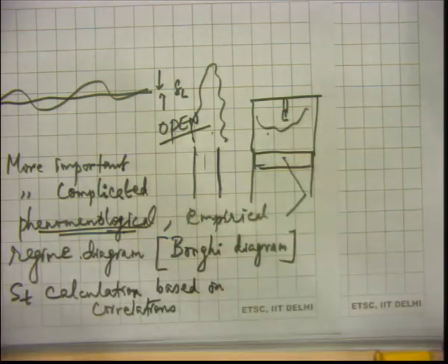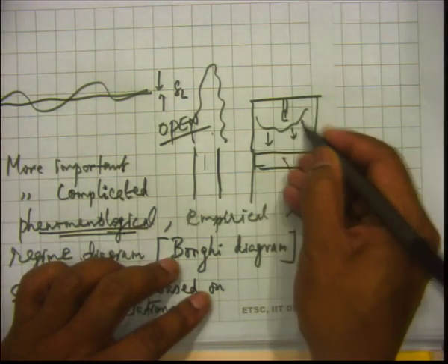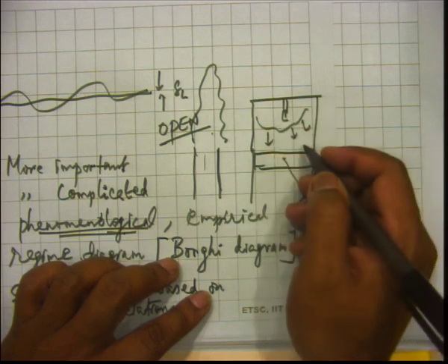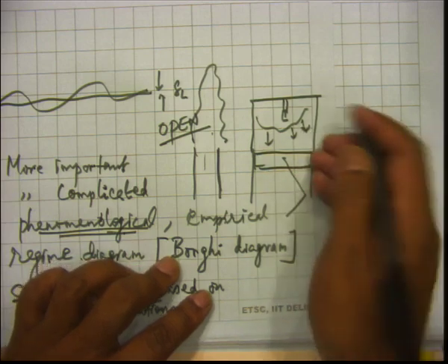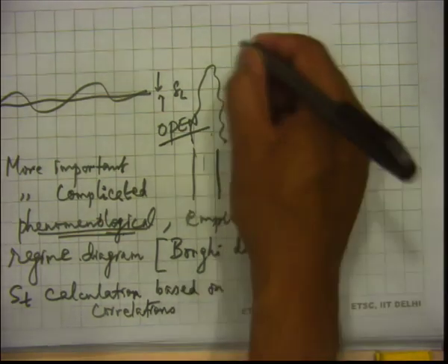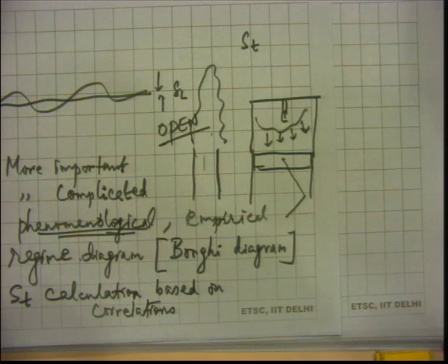So, this SI engine application, this is the turbulent premix flame, this has a flame which will keep moving, there is no question of anchoring it, because you do not want it to be anchored, you want it to move, right. And for SI engine applications, if you are familiar with IC engine textbooks, the ST calculation, the turbulent burning velocity calculation, is done with the help of laminar burning velocity and V prime RMS. And once you have ST, you can get m dot for the SI engine combustion situation, and m dot is important because m dot is related to engine power.